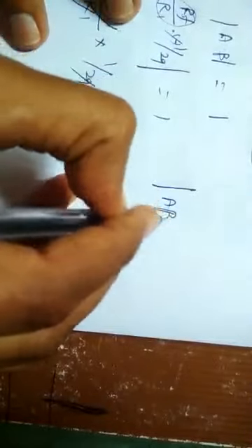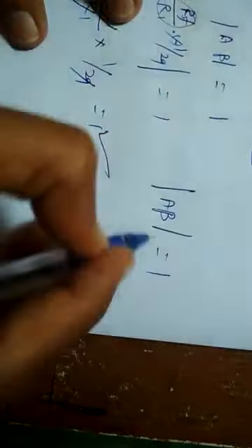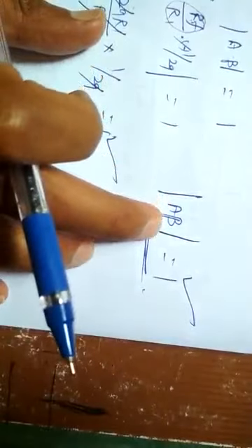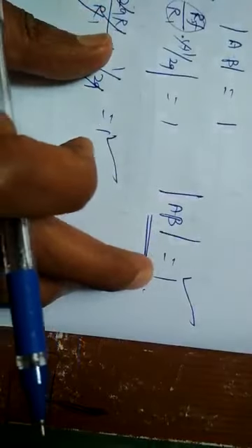So modulus of A beta equals 1. The absolute value of the product of the forward path and feedback path gain is proved as unity by considering only the value of RF equals 29 R1.